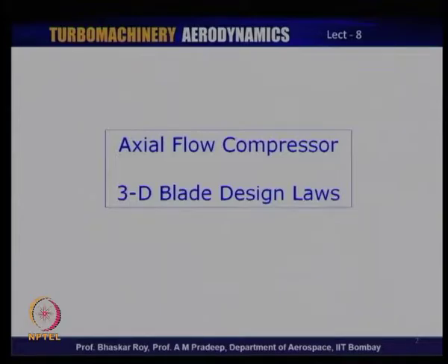Now, these design laws of course start off with the free vortex law, which we set forth in the last class. We will look at this free vortex law a little more in detail, and then we will see that it has a number of restrictions, because it was derived based on certain simplifications, and we will have to see how these simplifications can be got around for more modern, or rather more specifically more highly loaded, axial flow compressor blades.